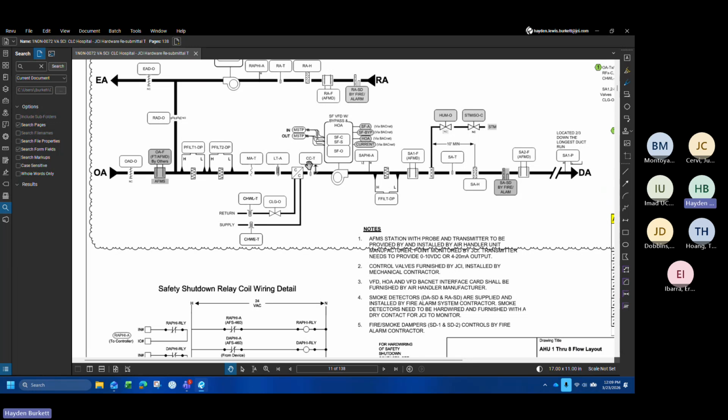This would most accurately get you your temperature differential between that and the mixed air temperature. So not necessarily from a troubleshooting standpoint, but from a control standpoint, we would be able to tell whether it's doing the appropriate amount of cooling based on the difference between our mixed and our cooling coil temperature. This differential between these two would effectively tell us how effective our loop is.